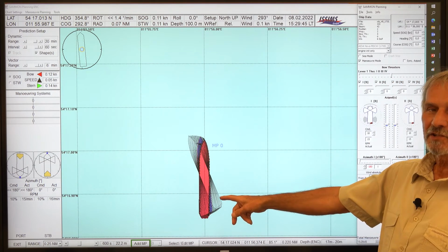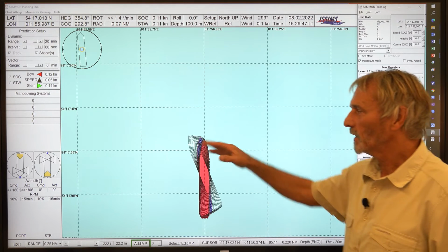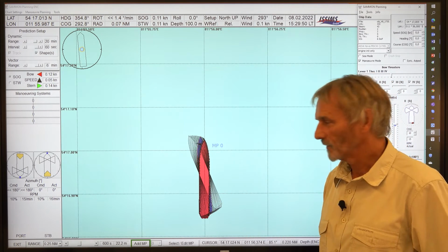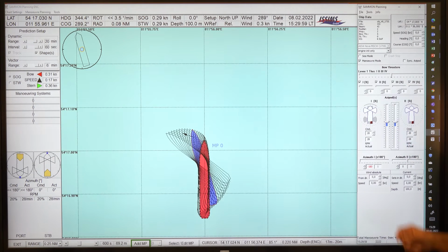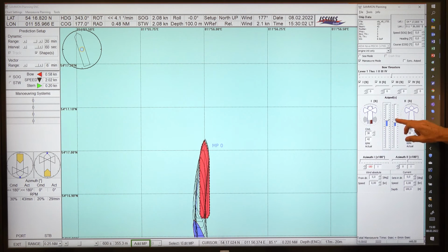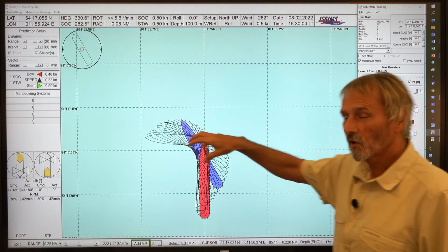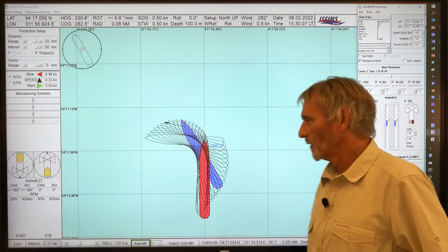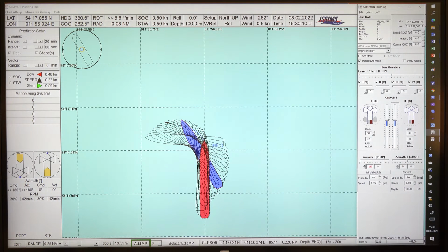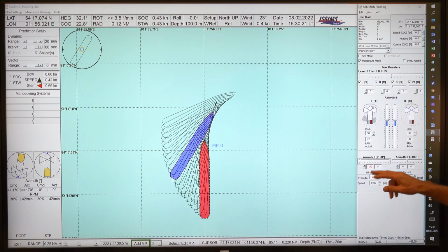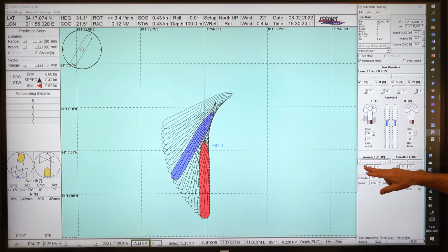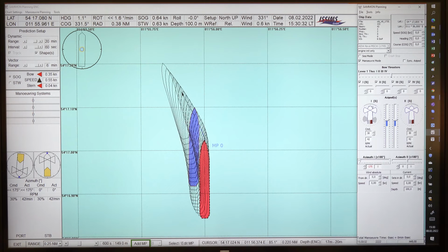So you see immediately the effect that there's a turning effect because of the shoulder, you know? And if you increase the revolutions ahead, then this turning effect will be bigger, 30%. So this is a turning only by the shoulder effect. What you could use is then to say, okay, I will use this pod on that side a little bit to create a thrust in this direction.